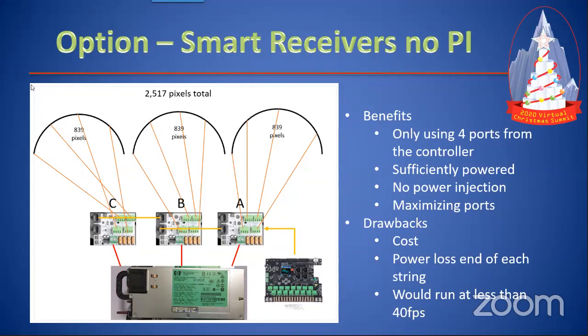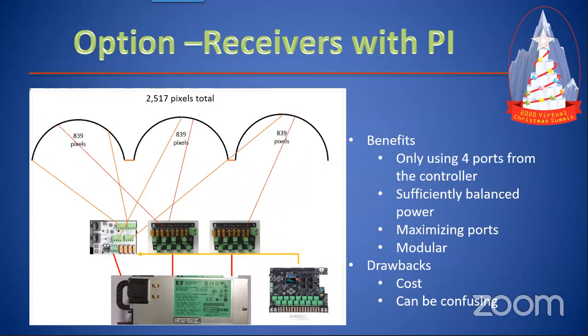Can you tie grounds of power supplies together instead of using a pigtail, and then send power and ground from a distro board? You will always want to tie your grounds. No matter what, even if you're using receiver boards or any other manner, your grounds are always tied. But it's definitely best practice to tie your grounds, because when you have ground loss, you're going to have flicker.